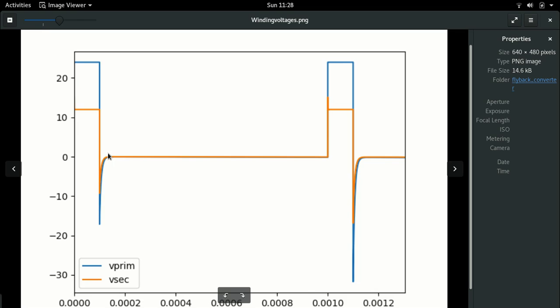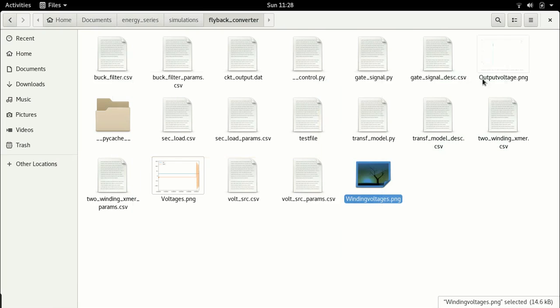When the switch is turned off, the voltage across the primary is 0, right? Now the voltage across the secondary is also 0. Now this might come as a surprise to you, because at this point you might think that the secondary is indeed conducting, right? But it's important to understand that the way it works in the simulation, this is not a physical voltage that appears, but rather this is the discharge of the induced EMF, right? So let's keep going.